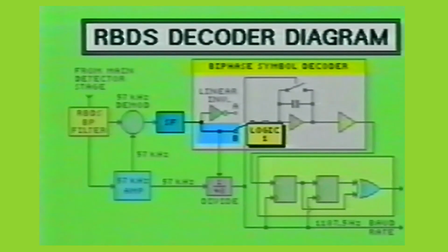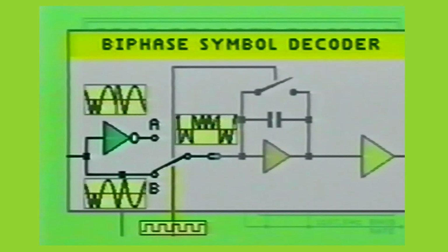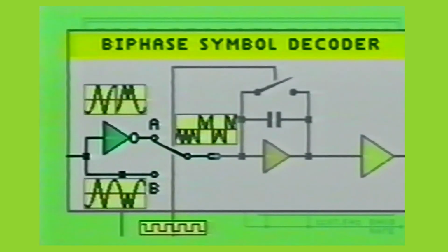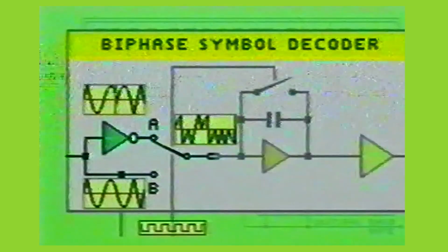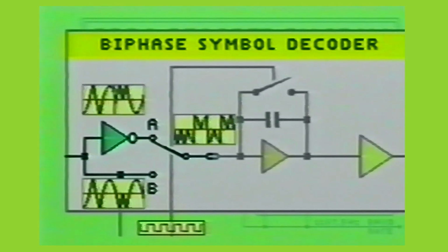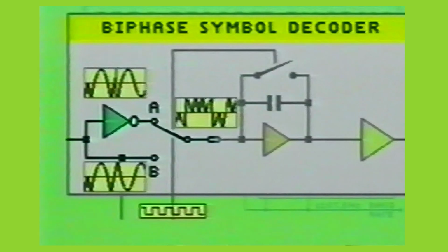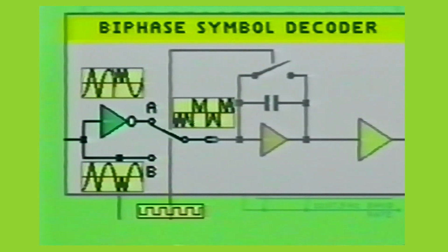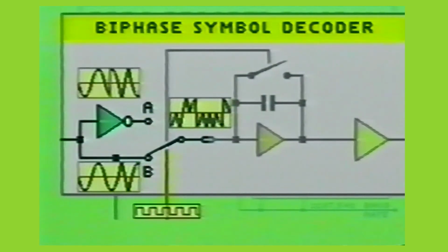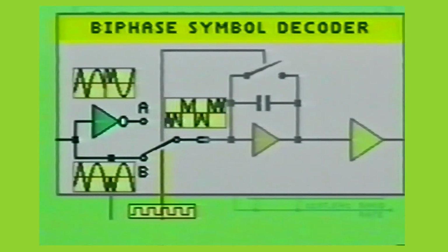As the single-pole double-throw switch receives the toggling pulses from the bitrate clock line, the low pulse interval will select input A, which will pass the inverted version of the filtered RBDS waveform through the switch for the duration of the logic state on the clock line. This process effectively decodes the waveform shaped by the odd impulse pair generated with the RBDS encoding technique previously described.